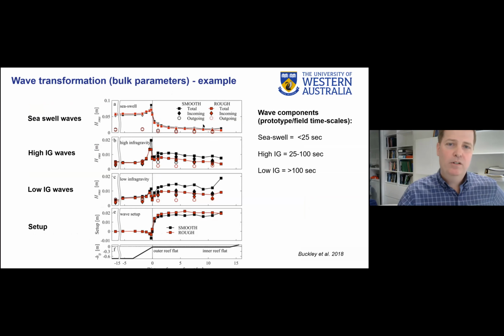I won't talk about all the fine details because I'm going to get into them in the results later, but I just want to show the type of information that we get. What is shown here is one wave case and water level case where we compare the smooth case and the rough case. We can get detailed measurements at all of those locations, and we can decompose the wave heights